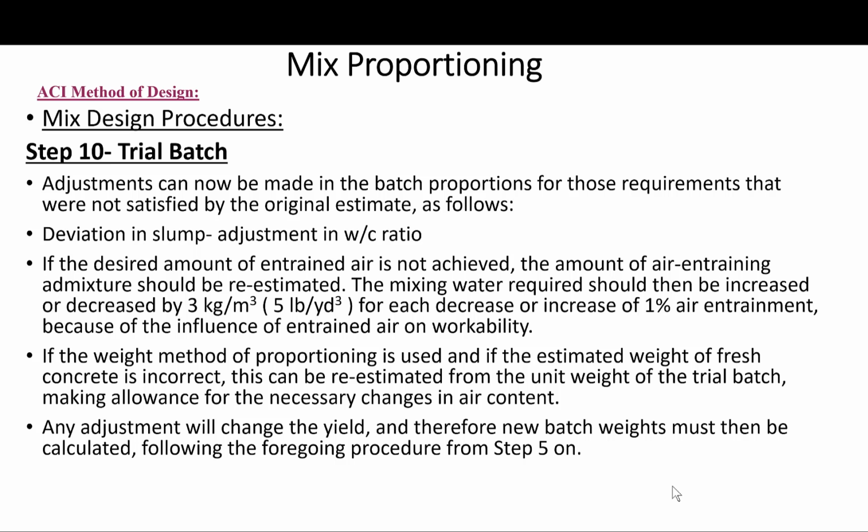The second thing, if the desired amount of entrained air is not achieved, the amount of air entraining admixture should be re-estimated. So the mix water required should then be increased or decreased, okay, by 3 kilograms per cubic meter for each decrease or increase of 1% air entrainment, because of the influence of the entrained air on workability.